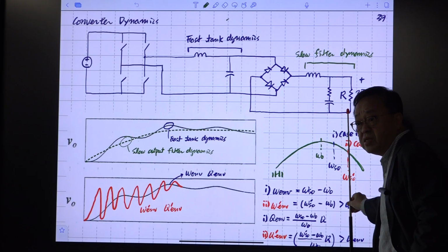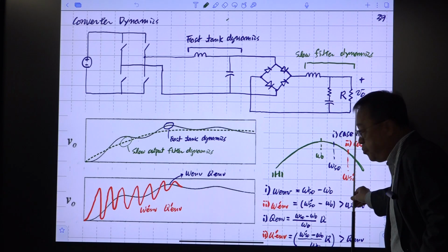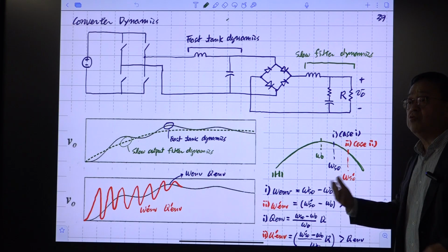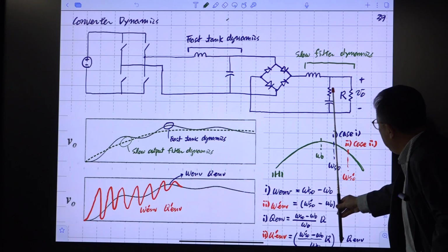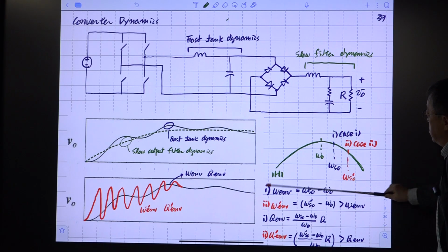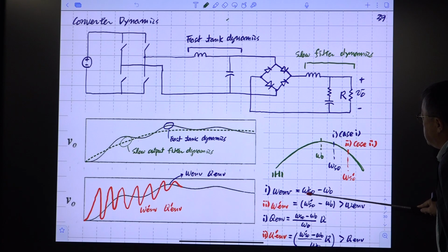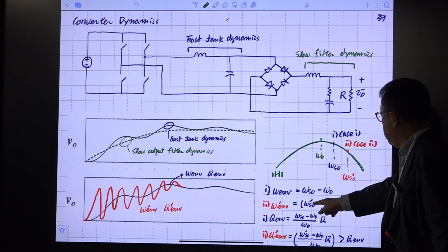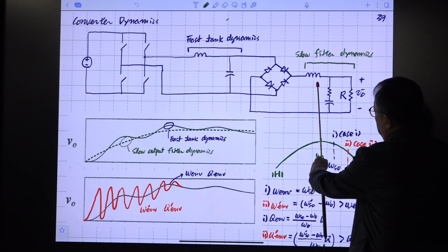It's the same as changing your duty ratio from, for example, 0.5 to 0.3 in the PWM case. But there is a huge difference because this is omega_s0, and with this blue line, we call it case number 1, that omega_nb is the difference between this and this, and the difference is relatively small. If you increase this unmodulated switching frequency, then the omega_nb will be this much.